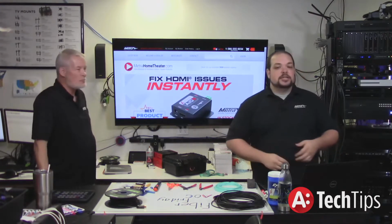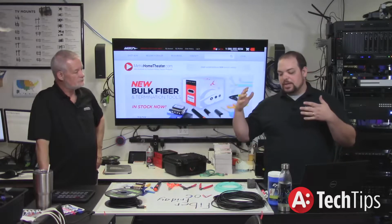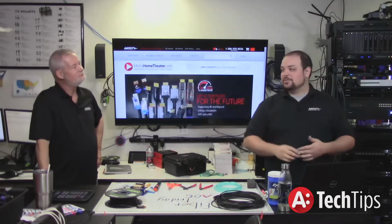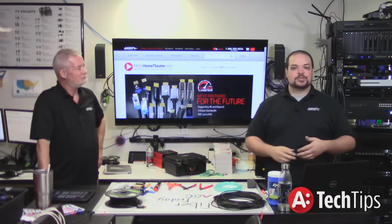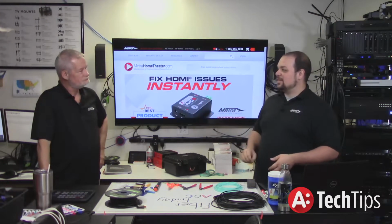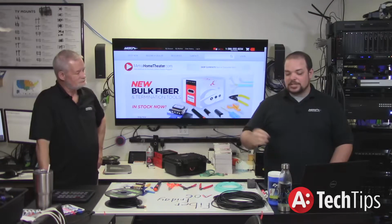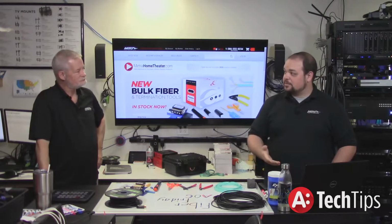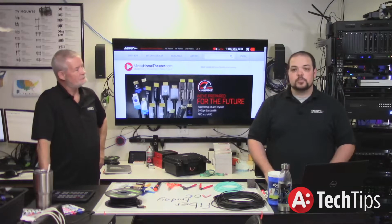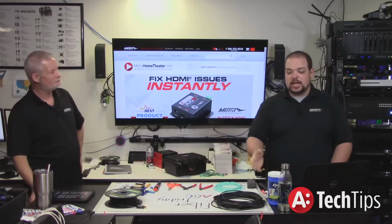There you go. So what we're going to talk about today is the differences between bulk fiber and AOC, because the C in AOC is cables, so saying AOC cables is a little redundant. But to make things simple, AOC cables, what's the biggest difference? Well, this actually came from a question from one of our videos from a couple before, the HDMI one, about what do we do with an AOC cable, or what's the biggest difference between AOC and a bulk?